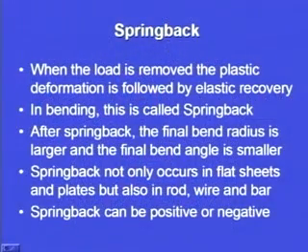Spring back can be positive, or in some cases, in case of some metals, it can be negative also. It depends on the conditions under which we are trying to bend. Depending upon the conditions and the requirements, the elastic recovery will be either positive or negative. Thereby, we can say that spring back can be positive or can even be negative. So, now we have to devise some ways in which we can avoid this phenomenon of spring back. How we can avoid spring back, we will see in the subsequent slide.